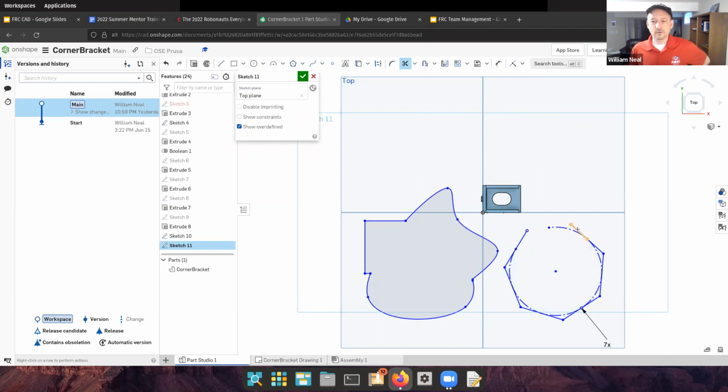Oh, look at this. I can do one at a time. What if I go in the center one here? Does it trim? No, it doesn't, but I can continue trimming these ones here and erase everything. So there I have some drawing tools, and then in my sketch, these are the sort of tools to modify my sketch. I'm not going to get into these too much at the moment, but I can mirror or create a linear pattern, or I can insert an existing drawing into my sketch and so on.